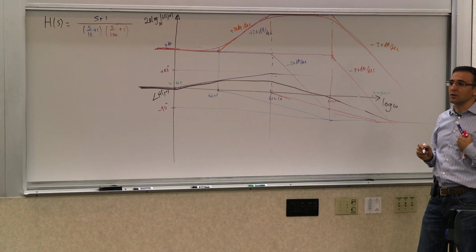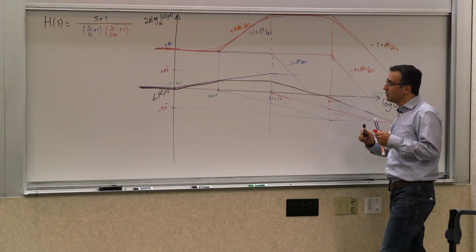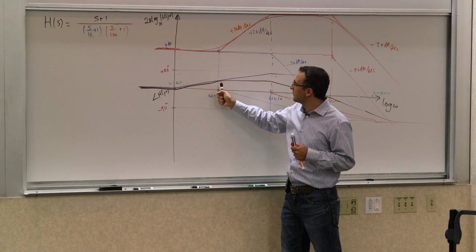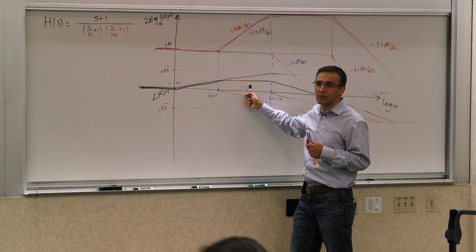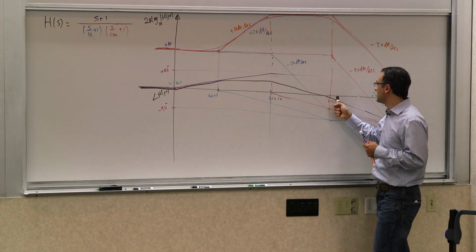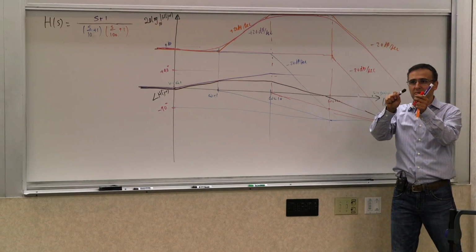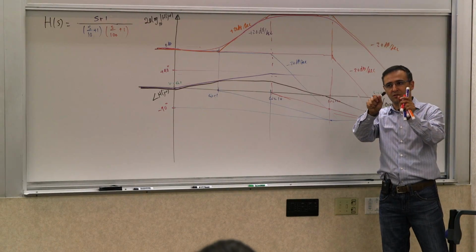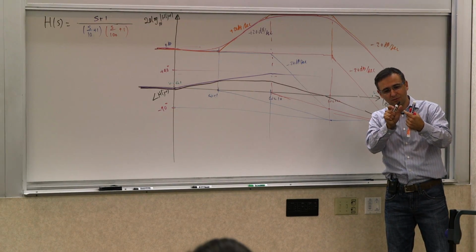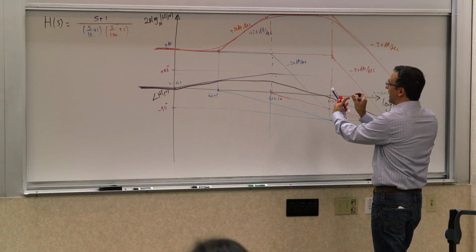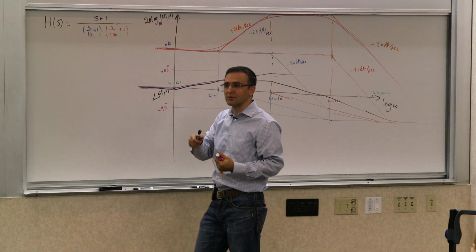So that's the phase response. That tells you that as the amplitude is increasing, the phase also starts leading first, becomes positive, and then it goes back to 0, and then it goes lagging. If you look at the phases of the sinusoids, you will see that for a system like this, the output starts getting ahead, and then it goes back, falls behind as you increase the frequency.